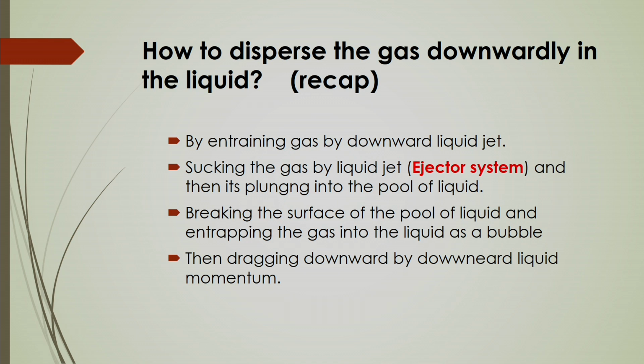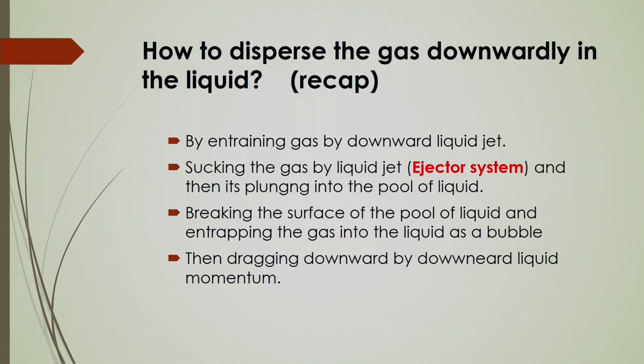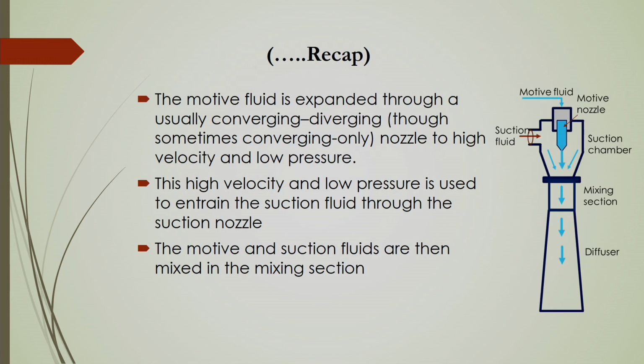In that case, this ejector system will suck the gas from the atmosphere or from any other source by the liquid jet, and then pump it into the pool of the liquid. The breaking of the surface of the pool of liquid and entrapping of the gas into the liquid as bubbles, and the dragging downward by the downward liquid momentum, is the more important phenomenon, where you can get more residence time in that particular downflow system.